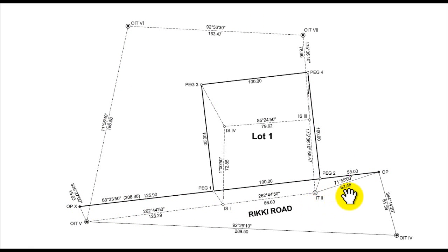And what we want to do is to create a 100 meter by 100 meter lot, approximately 55 meters from the old peg, and it will intersect onto that existing boundary there. We have through here some adoptions. These marks are no longer intervisible, or no longer are we able to find them, so we're also just going to prove the reliability of this old peg through here that we've tied onto here. This pegging tie through here is the original pegging tie, and we've found old peg X here.